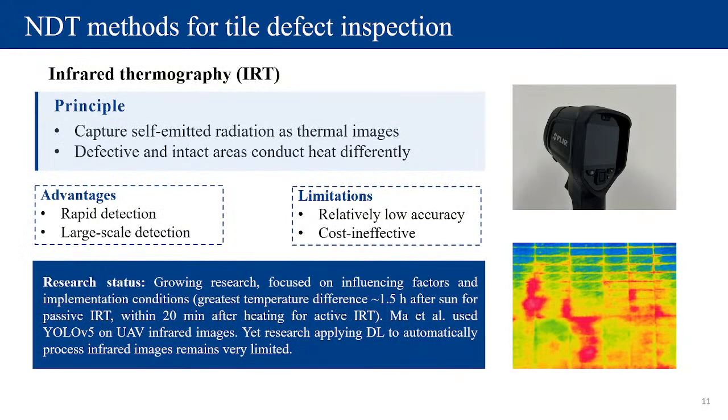And the second NDT method is infrared thermography, which captures the surface temperature of the tile facade, and the defective and intact areas could show the heat differently.